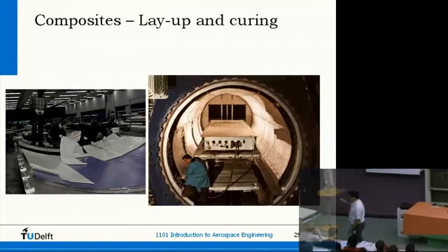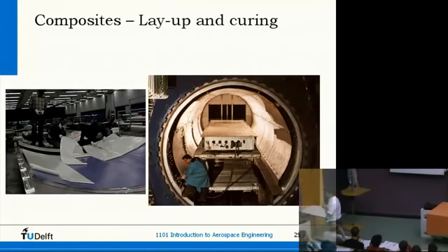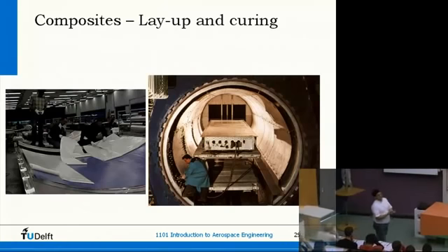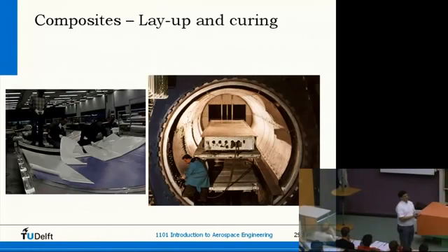Layers of fibers, in weaves, fabrics. Sometimes even the resin is already brought onto that weave, and then we have a so-called pre-preg, pre-impregnated fabric. What we do in composite manufacturing is building up a structure by putting layers on top of each other, for instance, in the layer process. Once the whole stack is completed, you put it into a nice foil, into an autoclave, and cure it.